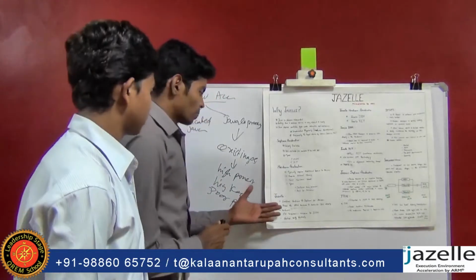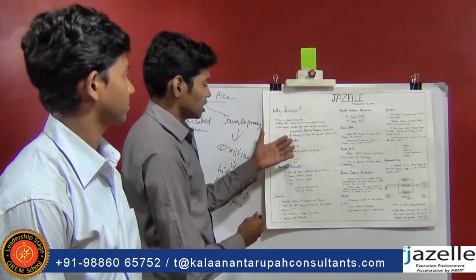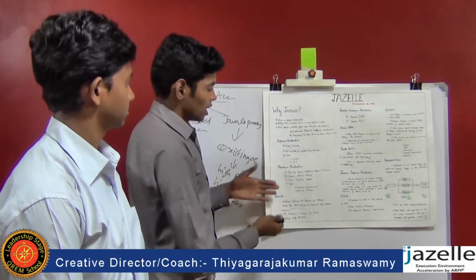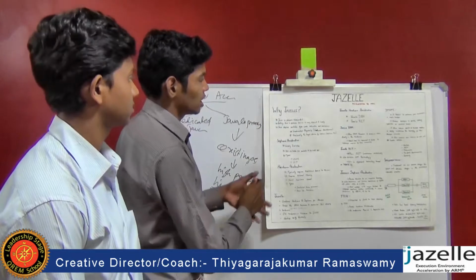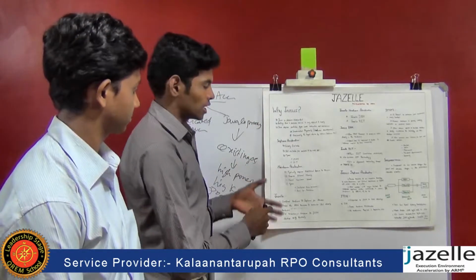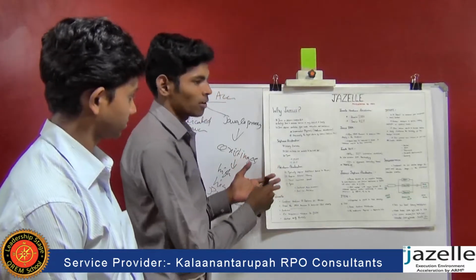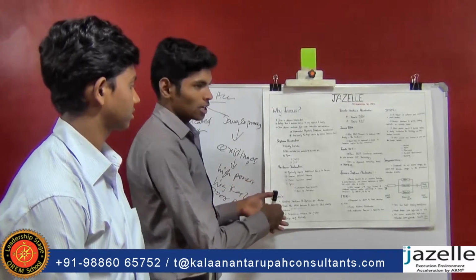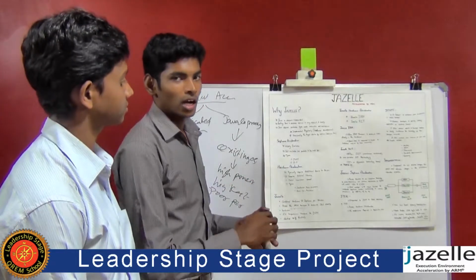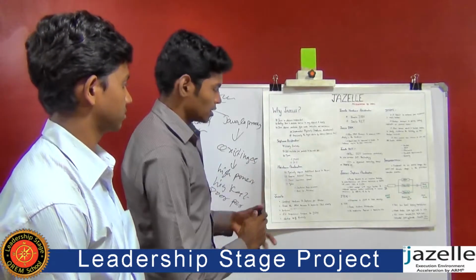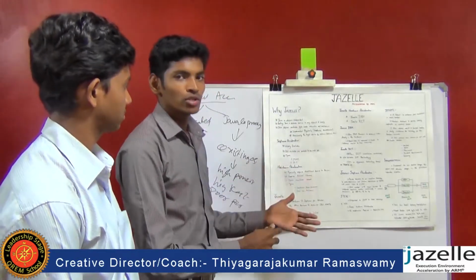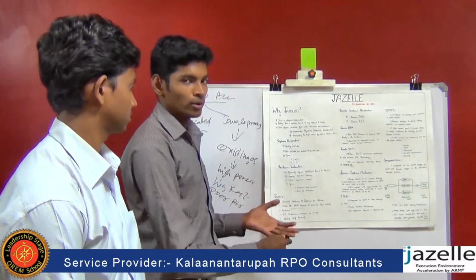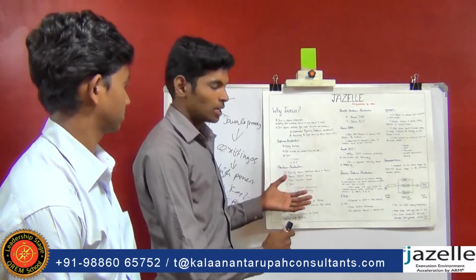Thank you. Why was Jazelle created? To overcome these disadvantages that my friend mentioned, Jazelle was created for accelerating the process and reducing power consumption and memory consumption. These are the reasons to create Jazelle. The Jazelle technology combines hardware and software and provides the solution for these problems. It enables the processor to execute the Java bytecode within the processor itself. And the Jazelle technology provides a virtual JVM, that is the Java virtual machine.